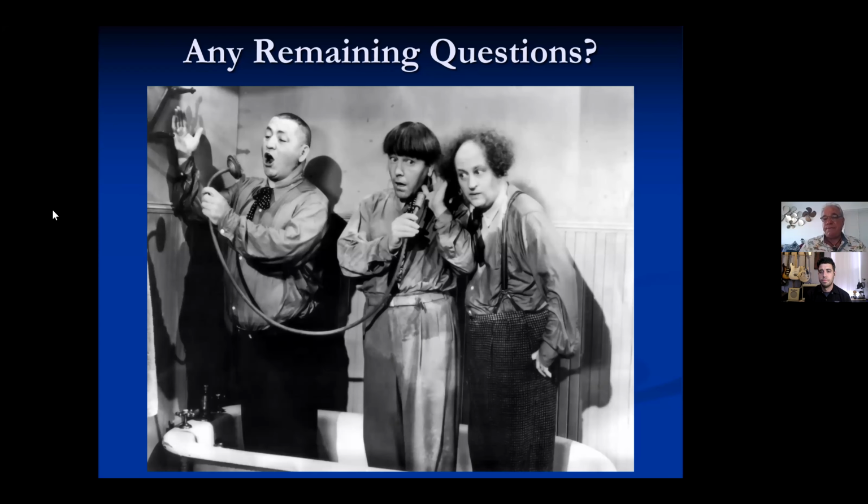Because now you have an unfiltered amplifier out there. Again, the only one I'm aware of that has a switch is a Shure, and hopefully someone could answer this for me, because I don't even know if that attenuator switch is before the amp, after the amp. Does it bypass the amp? Regardless, if you're still using the full power of the amp, you're creating noise, regardless of whether you have 0 dB gain, 6 dB attenuation, or 6 or 12 dB gain. There's an amp in there, unless it's bypassed by that switch.